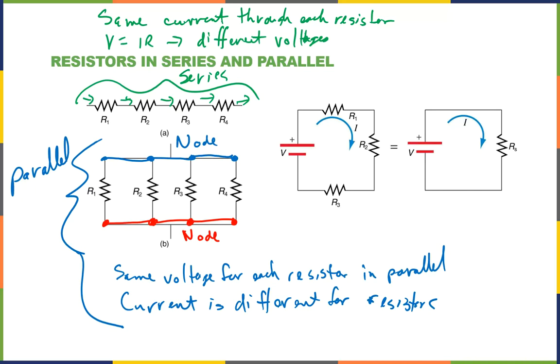So in something like, once again, let me pull the back off of this. In something like this, I have a bunch of batteries connected in here. And so they're either connected in series or parallel. How can I tell? Well, if I pop them out, I might be able to see how these things are connected. And the way they're connected is, there's a connection going like from here to here, and then here to here, and here to here.